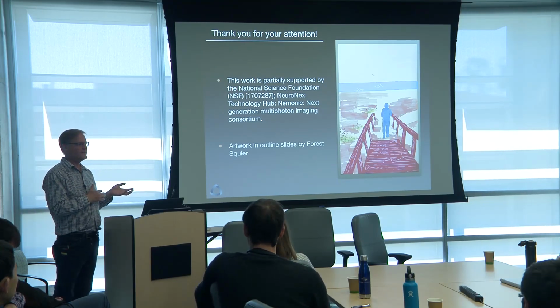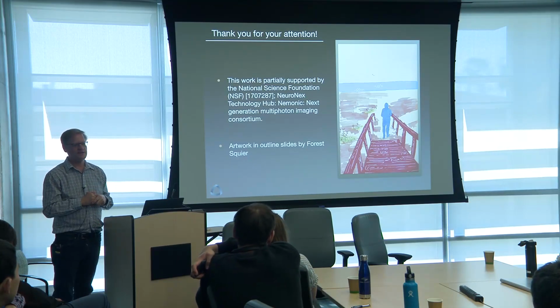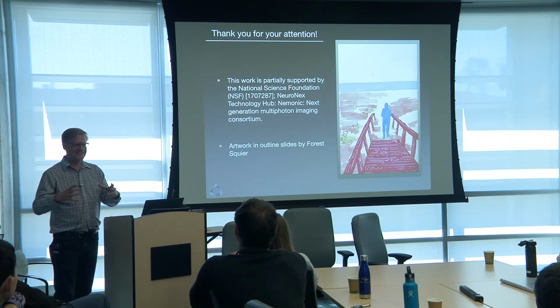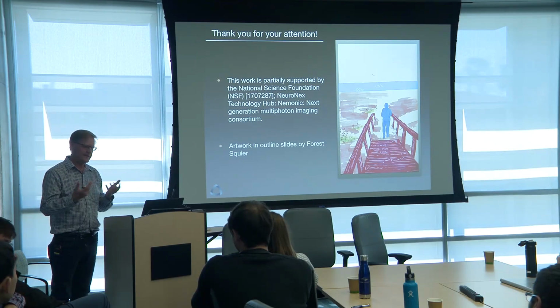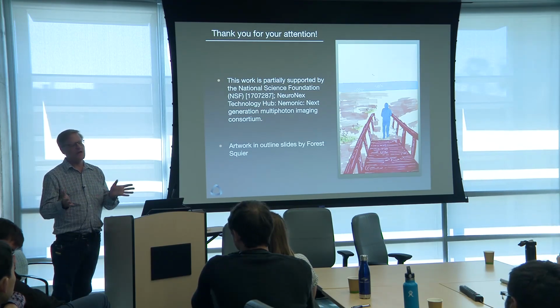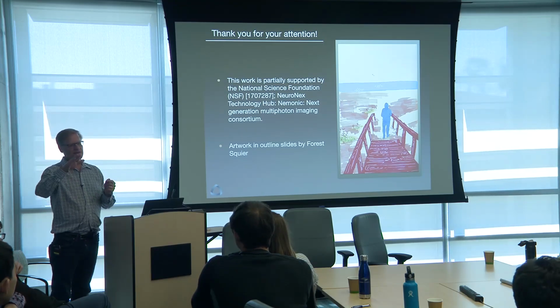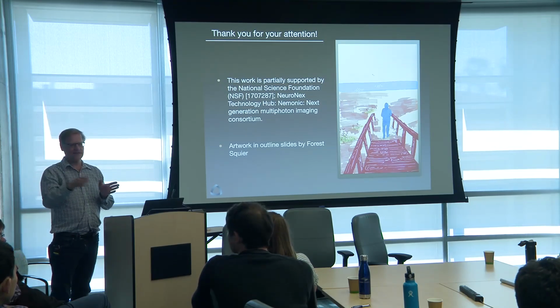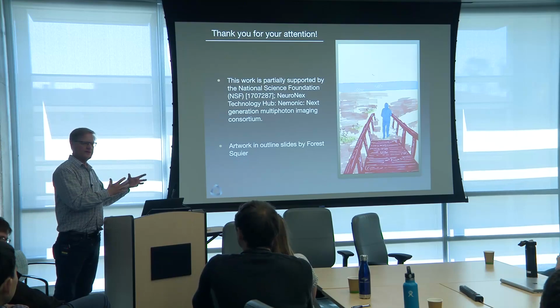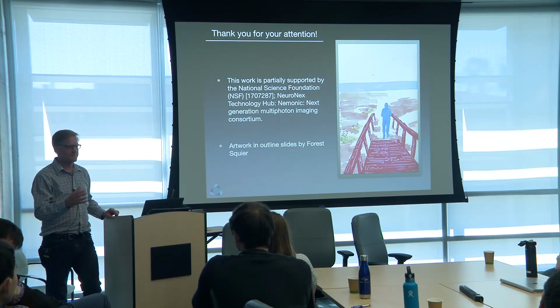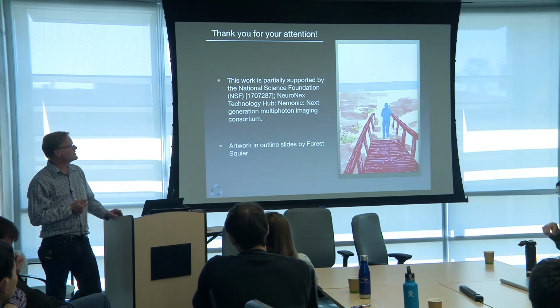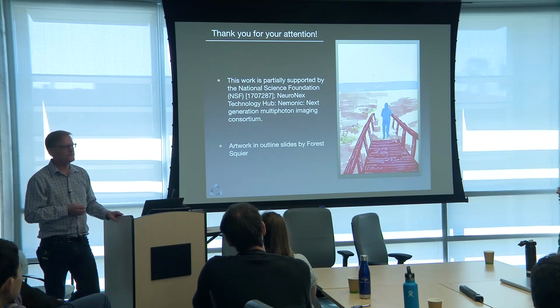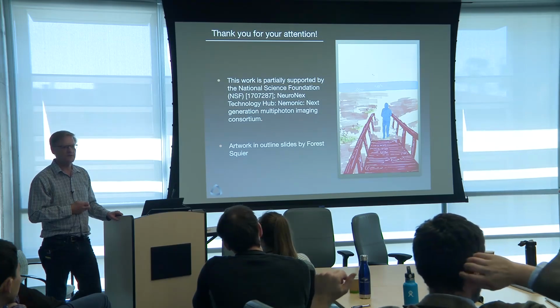So for a lot of what we do in my lab is materials processing, and it's just giant. You got a big part that you got to move through the system, and that would be an example of where we actually set it up to do both. So we've usually got a scan optic in there that allows us to scan certain areas, but then we can do specimen scanning to really put all these things together. So for micro machining with femtosecond lasers, it's a great tool to be able to do both, but the specimen scanning.